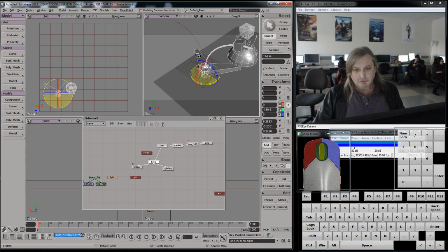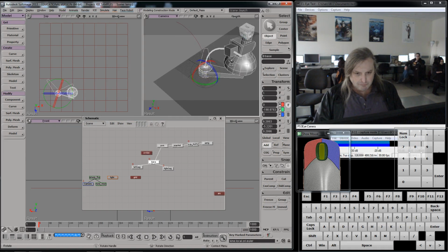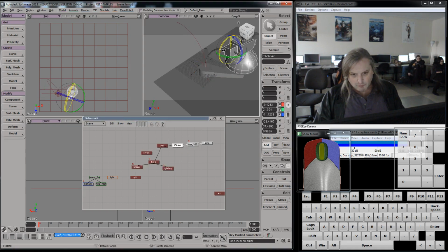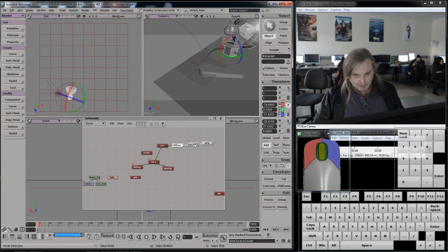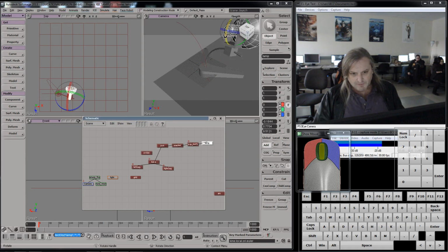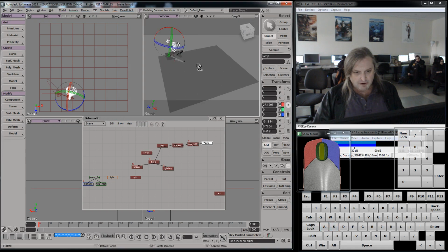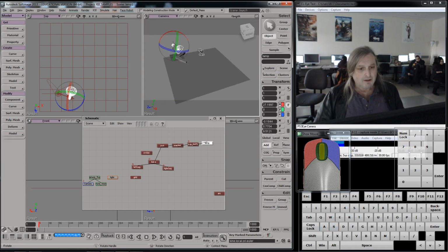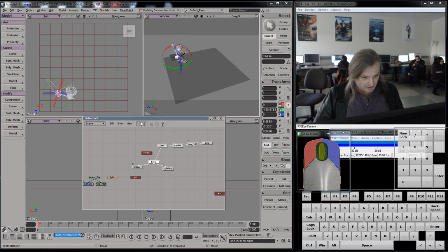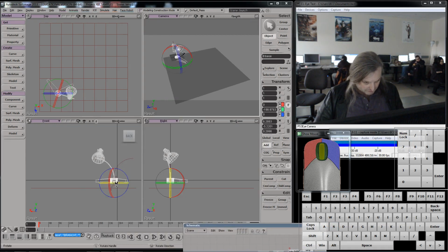Good. I'm going to start my lamp in this position here, and maybe I'll also move the head up a little bit. I'm going to go to the bracket. I'll rotate the whole thing like that, and I'll also take the lamp head itself, and I'll rotate it down so it looks a little bit more like my actual lamp over here, like that, okay? Now I'm going to start its movement. I'm going to take the base here. I'm going to probably lift it slightly off the surface. Oh, which it is. Good.